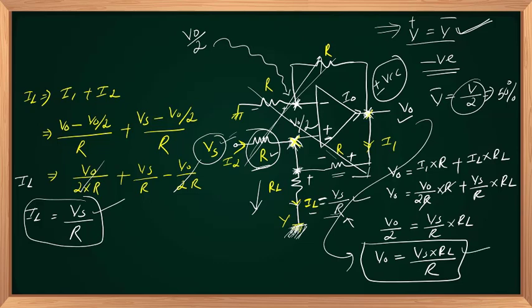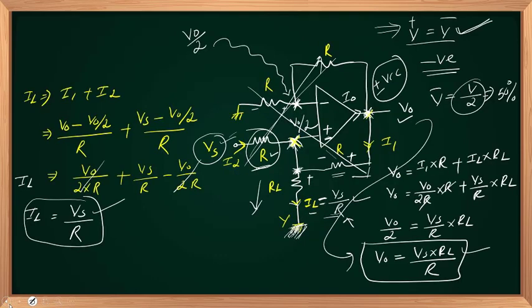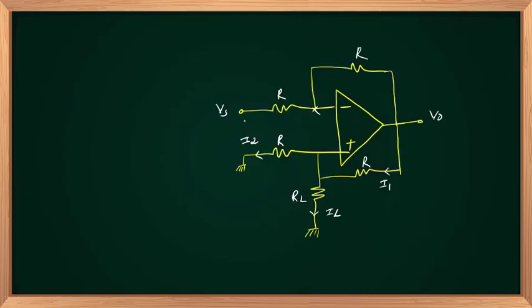Let us modify this circuit slightly. So we have another one. Initially Vs was connected here, so that Vs I am moving to the inverting side. All other parameters are the same. And in this case also, as we discussed earlier, these two are in parallel. So V plus will always be less than V minus. So negative feedback will be dominating in the circuit.